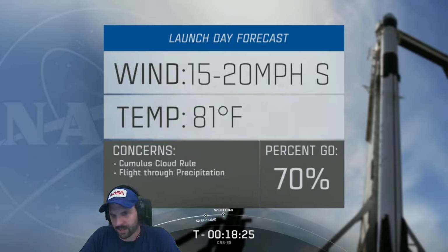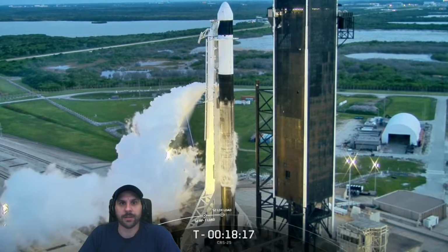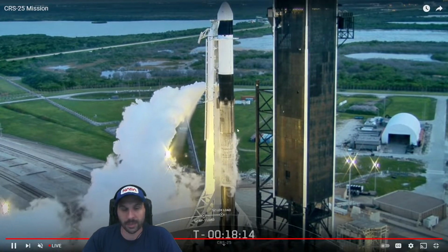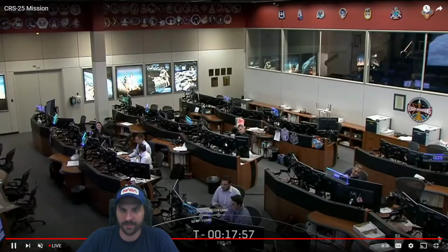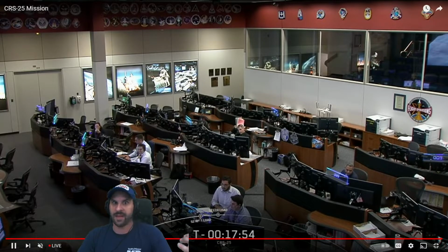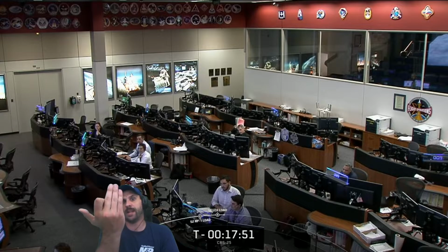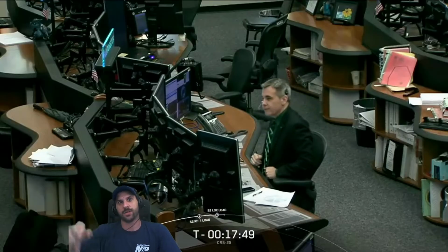Now, what does that mean? What do you mean? If they fill it up, the fuel's going to go somewhere? Yes, it will. The liquid oxygen that's inside boils off. It's really, really cold. Oxygen, that was mostly nitrogen that you're breathing. Oxygen likes to exist as a gas down here, so keeping it as a liquid at high pressure makes it boil. So they try to time it so they have the maximum amount of propellants before they get a boil off. So that's what that TE chill down on the side and that big vent was. They're basically filling up the fuel lines up the side of the transporter erector for the second stage to time it so the second stage and the first stage fill up with liquid oxygen at the exact same time.